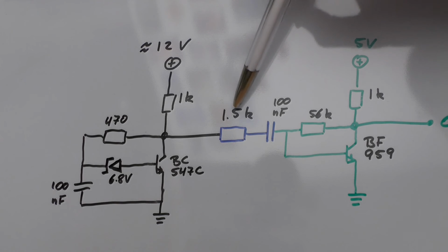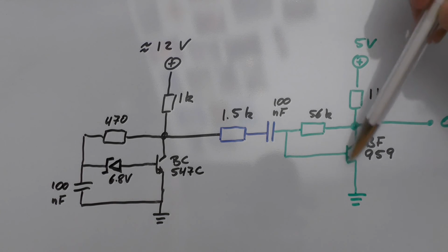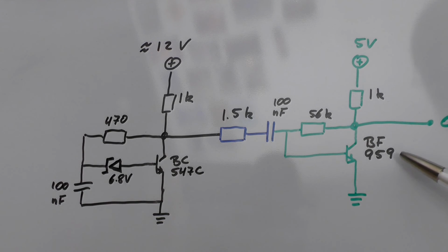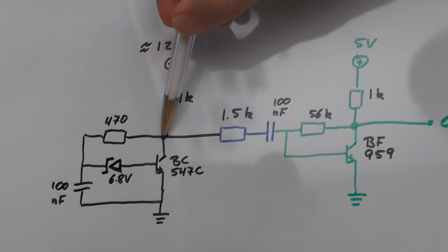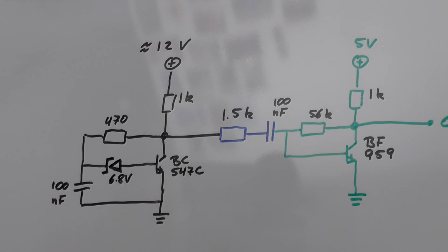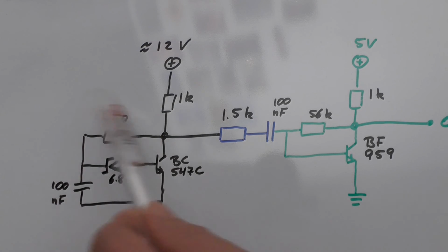And the resistors here and here pretty much determine the amplification with this transistor. And what we get here as output is what we've seen in the oscilloscope, which goes from about 0.5 to 4.5 volts or so, which is perfectly fine to feed at least into an Atmel microcontroller. So at this point we've measured here the actual output. What we can also do is measure here and take another look at what comes out at this stage.